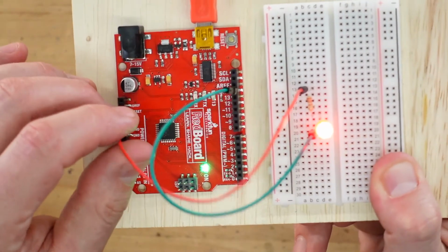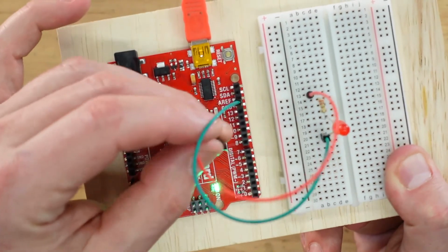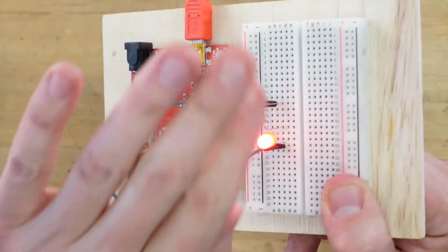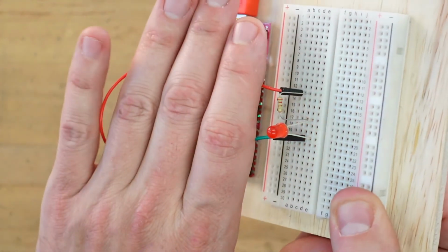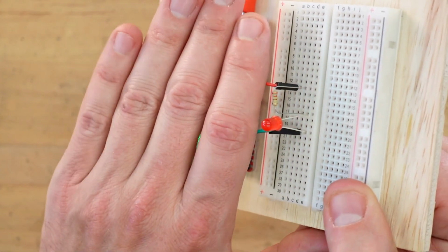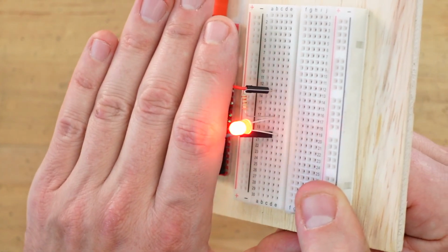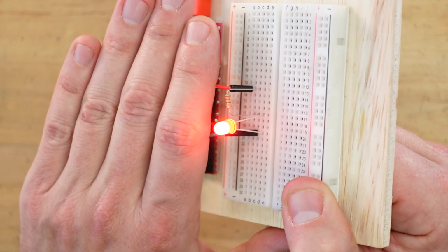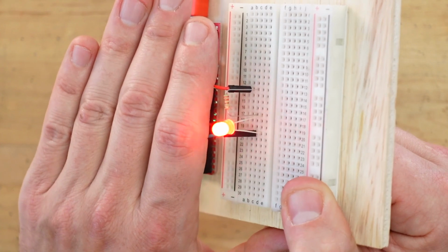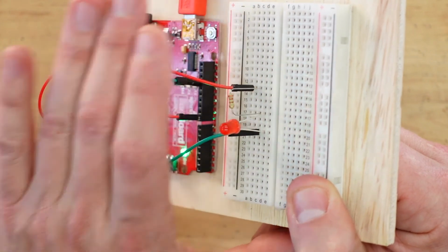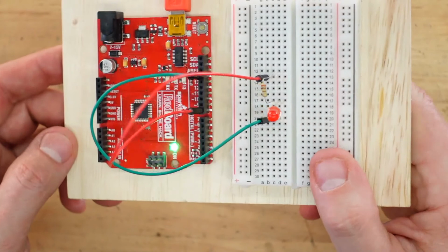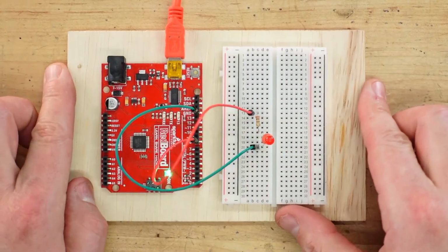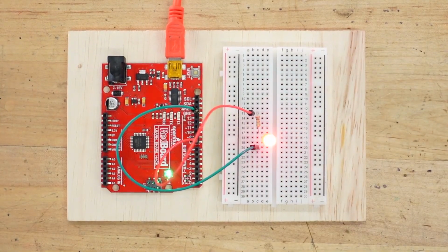If we move this jumper back to 8, you can start to understand what, as a digital output, Arduino is doing. All it is doing is saying, turn the power on pin 8 for 1 second, and then turn it off, and then turn it back on. So that is digital output. That is a super common basic function of any type of Arduino project. I'm going to pause here and get set up to do digital input.